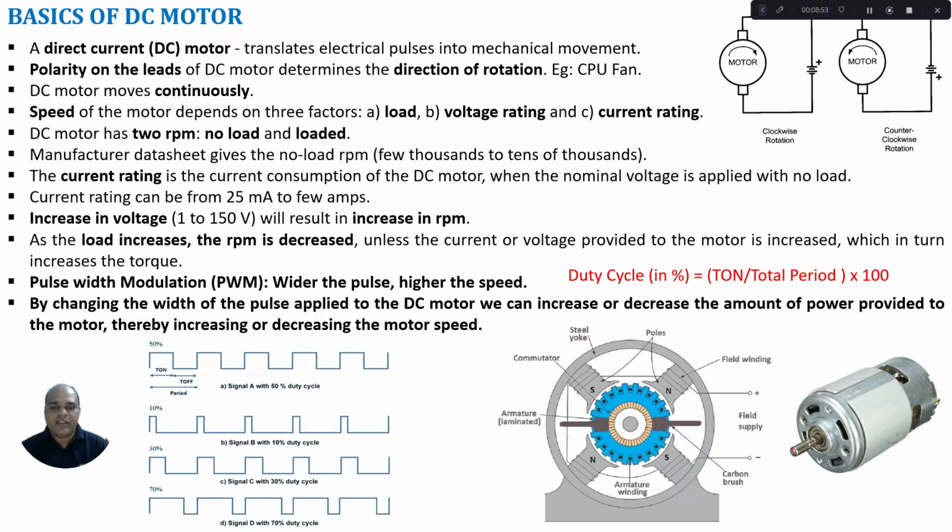And the second factor why we need to use an external motor driver is that any rotating structure will produce a back EMF. So this back EMF, when it comes to your microcontroller, might damage your microcontroller. So we should prevent that. We should provide an isolation between our microcontroller and the motor. In order to do that, we can make use of a motor driver IC.